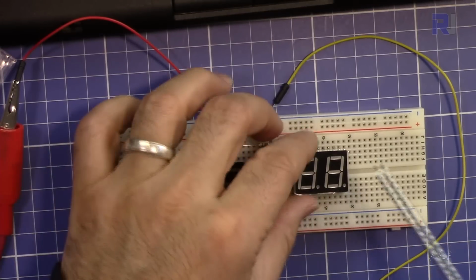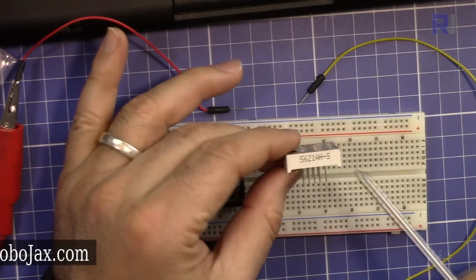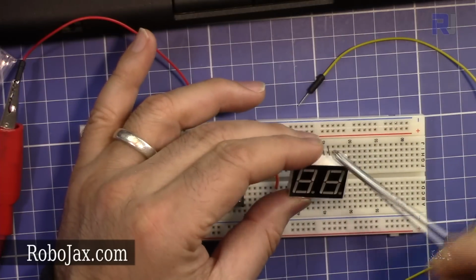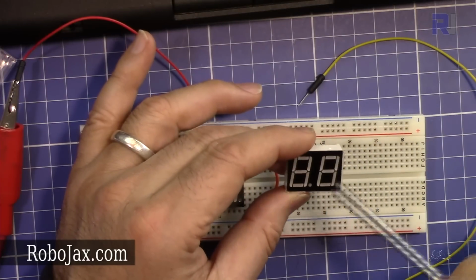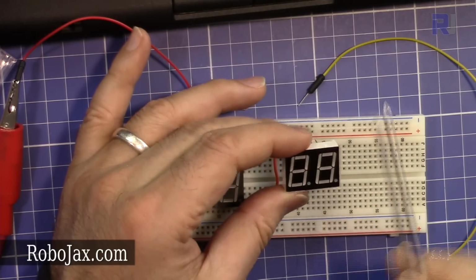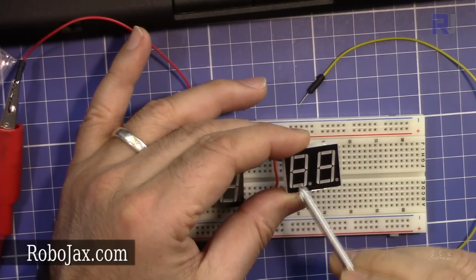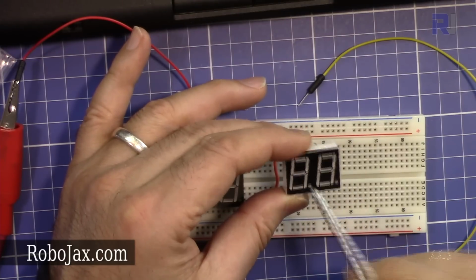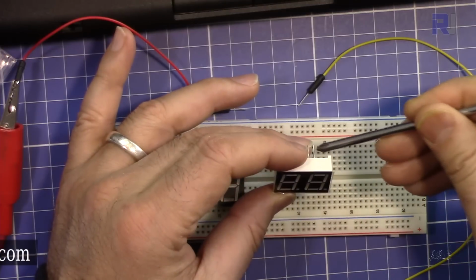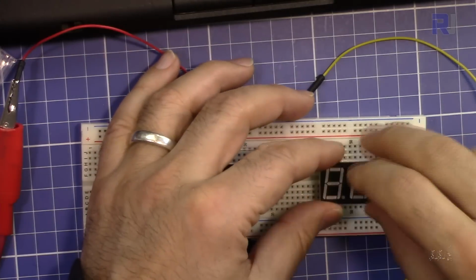And also we have a 2-digit display. In the 2-digit display, the number of pins does not increase. What it does is we have one common anode or cathode. In this case, this is common cathode for 1 digit, and we have another common for this one. So this is 7 plus 1 is 8, and also 7 plus 1 is 8. So we have only 8 pins for all of those. Depending on which common is activated, this will be turned on or off. So which I'm going to connect next.